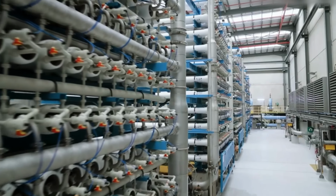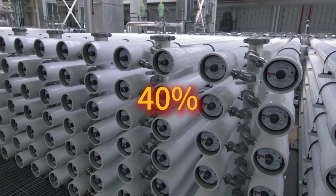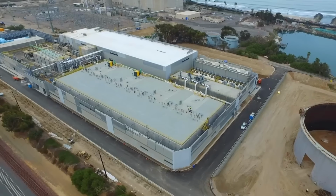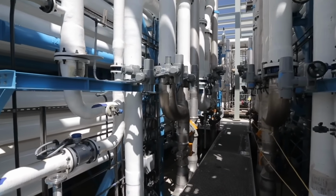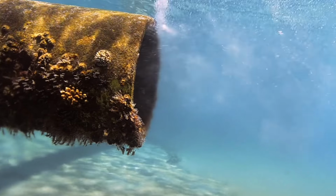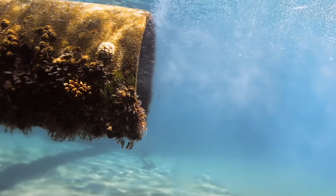But the system does not convert all of the incoming seawater into freshwater. Operational seawater RO plants commonly recover around 40 to 50% of the water entering the membrane system. If a plant operates at a 45% recovery rate, producing 1 cubic meter of freshwater requires more than 2 cubic meters of seawater to enter the RO stage. The rest leaves as a concentrated saltwater stream known as brine.